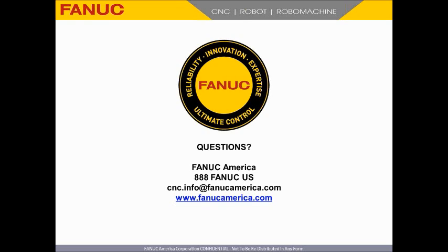Does a spindle have to be oriented on a mill? That's the question. I guess we're talking about, obviously probing on a mill. Yeah, okay. Yeah. Not necessarily, because most spindle probes today, when I first started, if you used a spindle probe, you had to orient the spindle probe so it would face the reader.